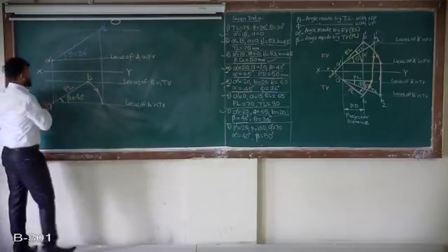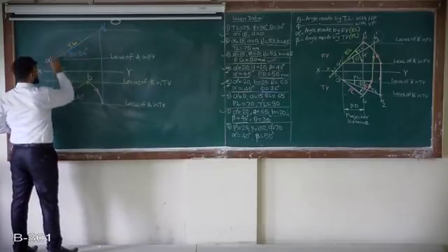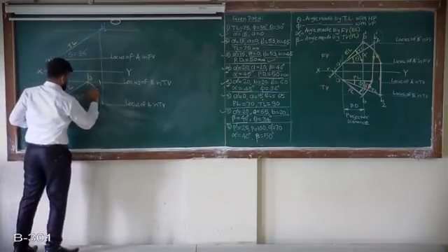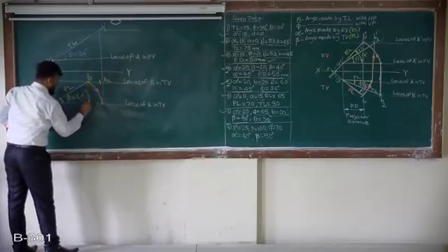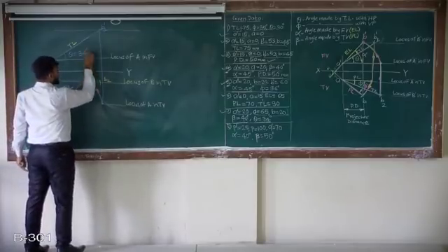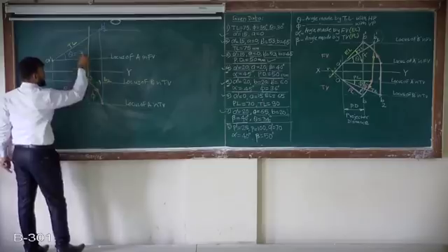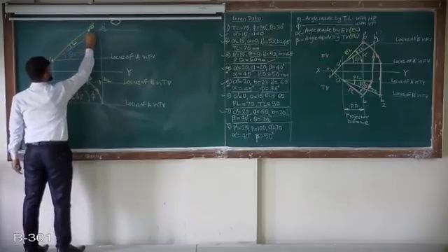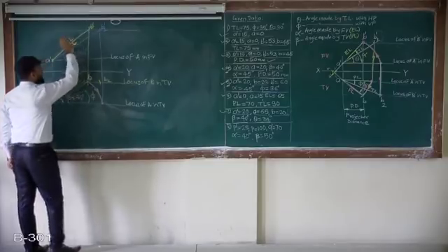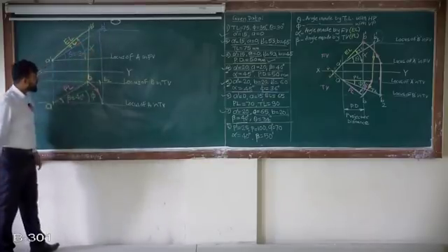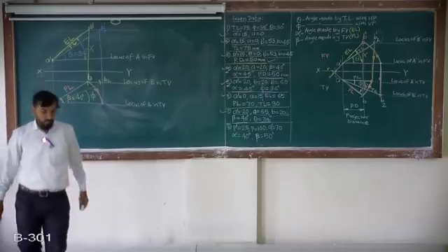Right? Now this is true length. Measure this true length, mark from this A onto the locus of B. This point will be B2, angle will be phi. You know this B point, draw the projector of this B, this point as B dash. Draw this line, this is true line and this is elevation length, and this corresponding angle made by elevation length is alpha. So that's whole problem.